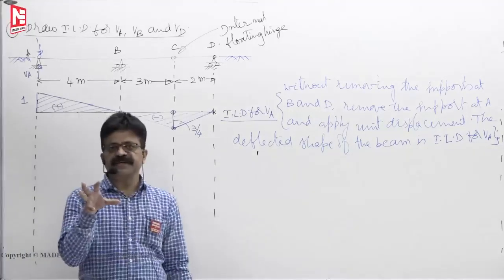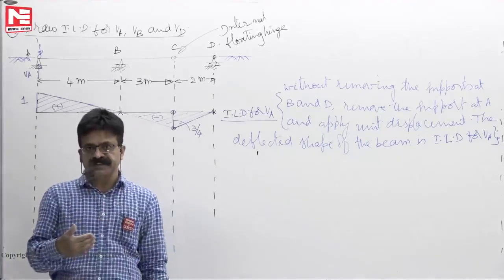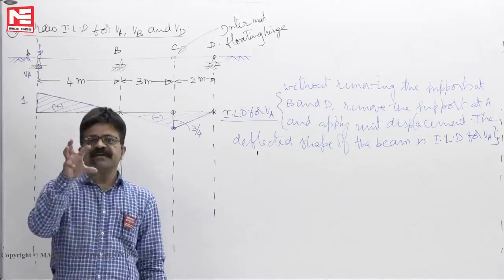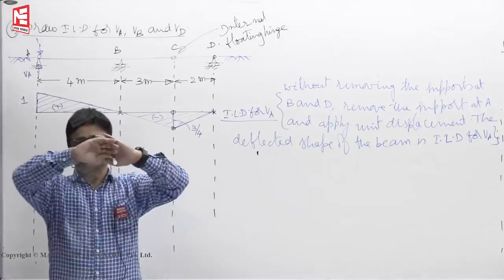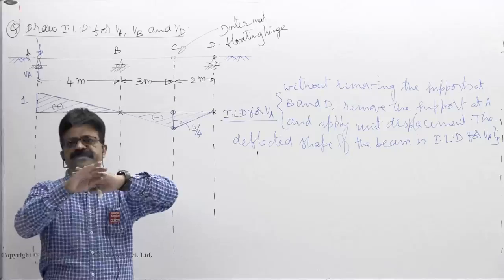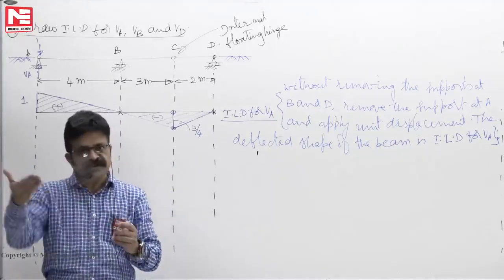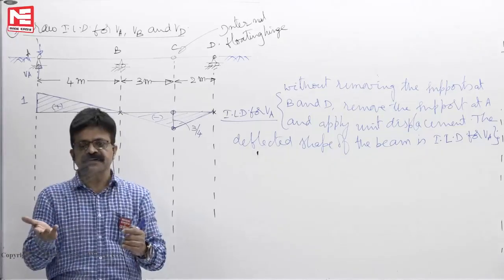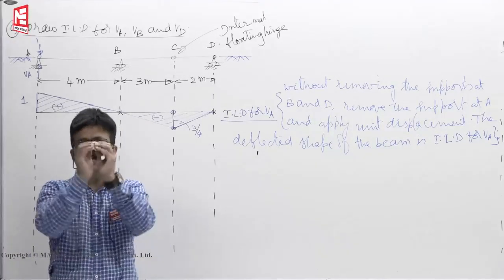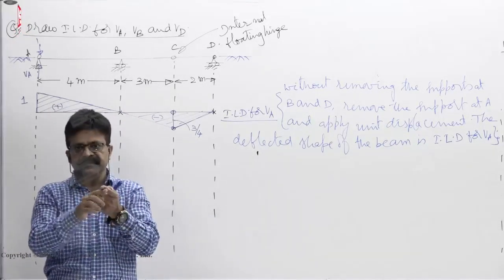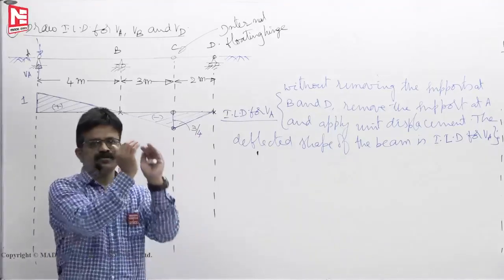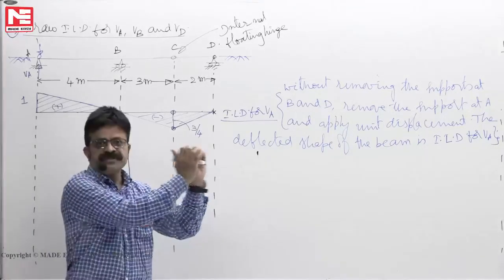So accordingly for 10 million times, you will take the fatigue coefficient. Then accordingly you put, say, in ordinary circumstances a 125 diameter pin. Now because you have to take care of the reversal effect also, instead of a 125 pin you have to put a 150 pin. So a thicker diameter pin you have to insert.